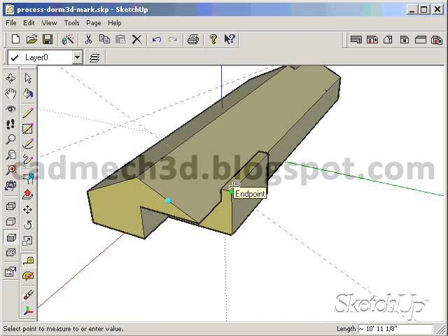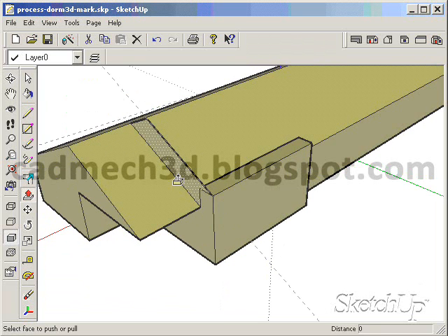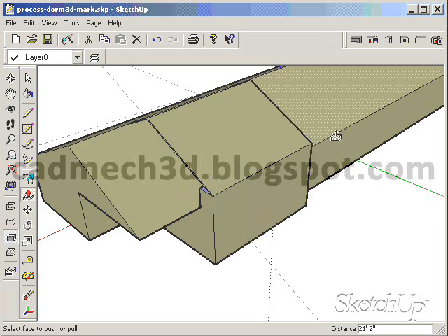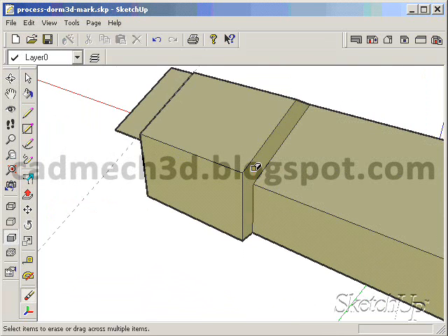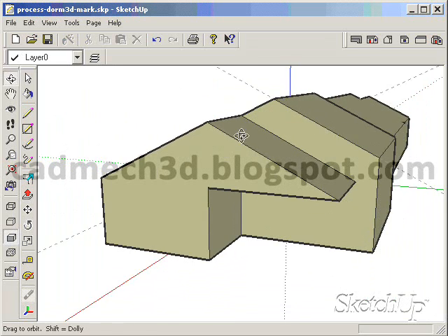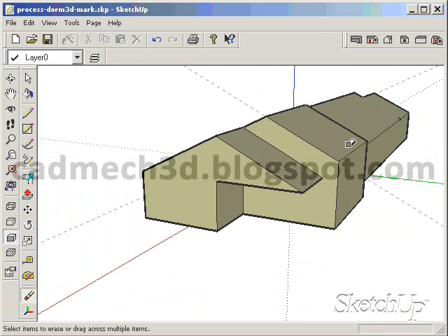For the higher shed, I copy the roof slope out by dragging on an edge with the tape measure tool and place it at the corner of the higher plate. Now with the pencil I can lock to infer along the direction back to the intersection with the opposite roof slope and draw back down to the main ridge. By closing this into a surface I can use push-pull. I can reverse the face to keep the outside color consistent. I pull it right over the top of the other roof and erase out the edges I don't need. I've now got the entire roof in place with proper roof planes at the correct slopes.